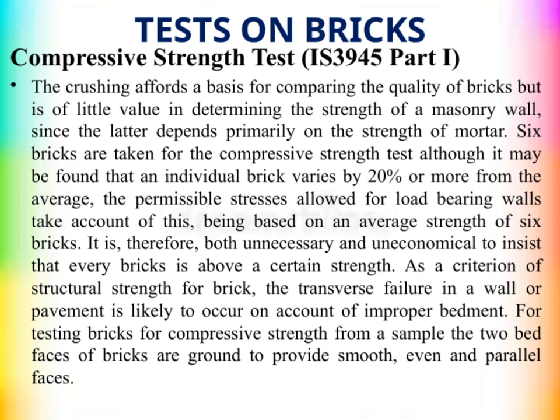When testing bricks for compressive strength, we prepare a sample by grinding the 2 bed faces to ensure they are smooth, even, and parallel. This preparation helps us get accurate and consistent test results, which are essential for assessing the quality of the bricks used in construction. So, in summary, this test helps us compare brick quality, but we must consider the broader context of how bricks perform in actual structures, especially considering the importance of mortar and proper laying techniques.